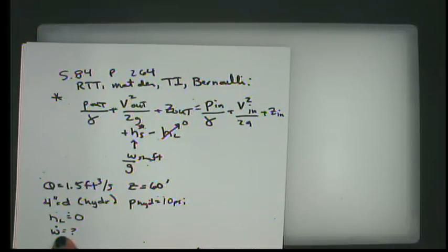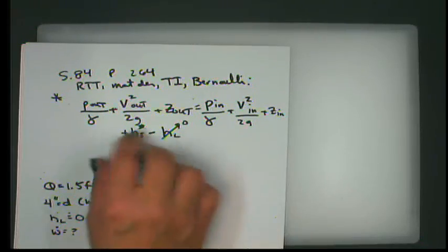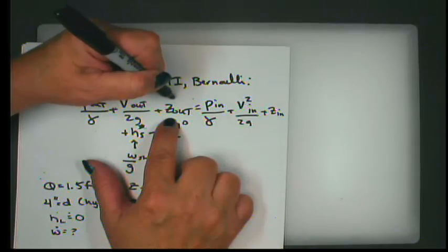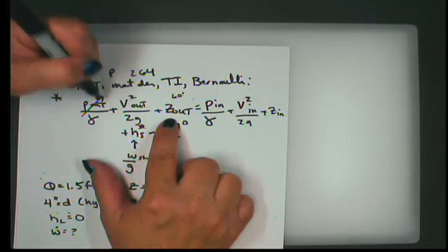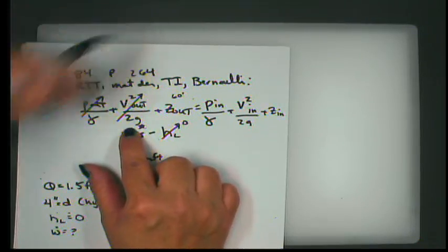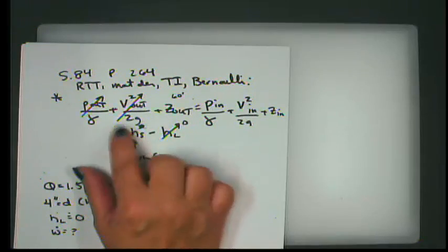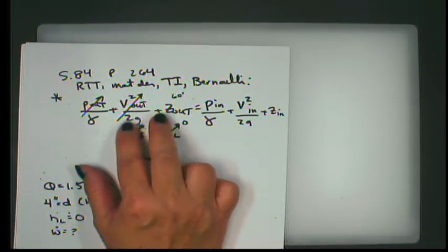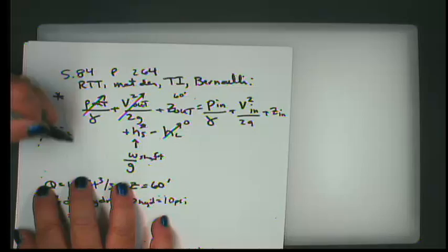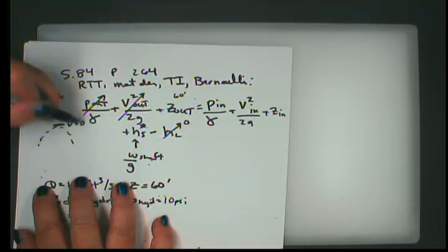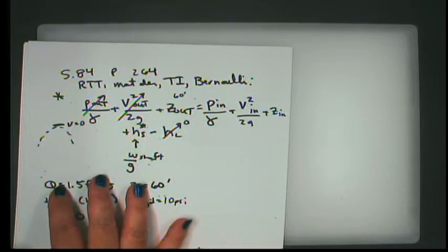If we consider what's going on here, if we call this the outlet, what we're trying to get is this 60 feet in the air. The pressure here is atmospheric. The velocity here, what's going to happen at the maximum velocity? Once again, you can come up with this thinking about the kinematic equations. When you reach the maximum height of an arc, the velocity here is equal to 0. That's what makes it be the maximum height. If there was velocity left, it would continue to increase.